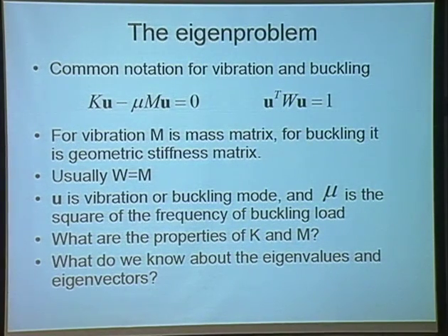And a homogeneous system either has the trivial solution, which is u equal to 0, which will be the case outside resonance. And when μ is equal to one of the eigenvalues, or one of the vibration frequencies, the matrix becomes singular, and the solution is no longer unique.